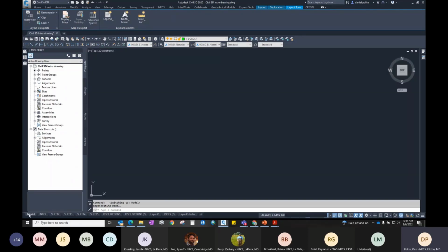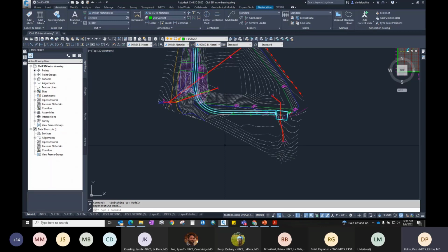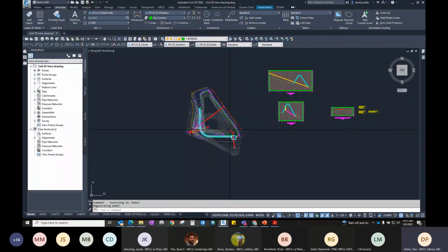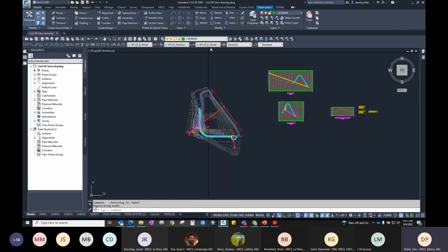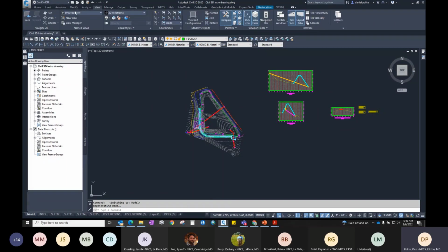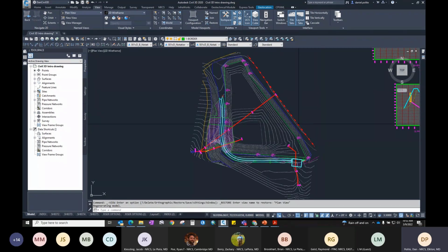Now, the fun stuff, the UCS. This gets people confused a little bit sometimes, but it's not as hard as it seems. The biggest thing on UCS is that it's just a way of displaying your drawing. And like I said, when you have named views, you can name those views based off of that UCS. So currently we have a named view of our plan view that shows this, basically showing north.